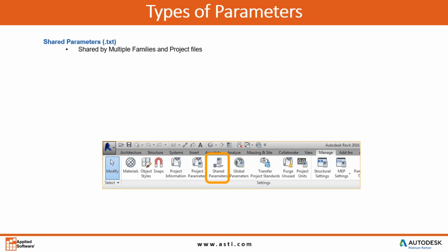If we're using shared parameters, that can go into multiple different things. So let's say it's some kind of serial number identification or something unique that needs to be visible and seen within multiple families. I don't want to go into each one and do it. This actually pushes it out into those. And if it's another project, could be multiple buildings within a complex or campus that I want to have this shared parameter. So that's one advantage, or two advantages of it.